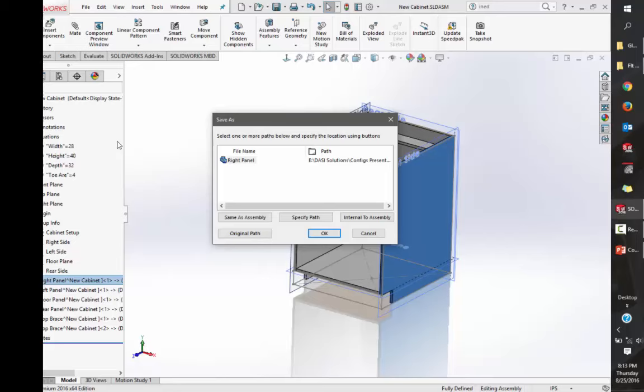Okay. And then next week I get another one, and I'm going to go back to that original file, open it up, Save As, and now I've got this own file. The problem we used to have traditionally, especially with top-down design, is that when you change the name of that original file or you save that original file as something else, all your external relationships broke. But because we're keeping the parts virtualized, they tend to keep that a little bit nicer. I don't have to go through the traditional rename window or SOLIDWORKS Explorer and hope everything works right. The virtualization helps compartmentalize that idea.